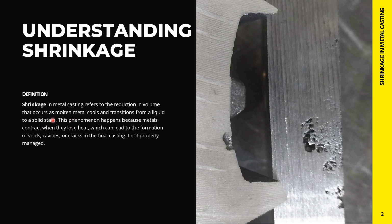Shrinkage is the reduction in the volume of a metal as it cools and solidifies during the casting process. Metals expand when heated and contract when cooled. This contraction is natural, but in casting it can lead to defects such as voids, cavities, or even cracks in the final product.